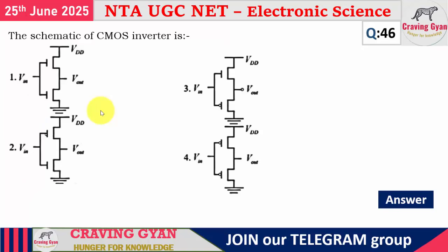46th question. Again, this is a simple question. The schematic of a CMOS inverter is given. Now look at the things. In the case of CMOS, you will be having a pull-up network and a pull-down network. For the pull-up network, you make use of a PMOS transistor, and for the pull-down network, you make use of an NMOS transistor. In the case of an inverter, you will be having one PMOS and one NMOS. That's it.